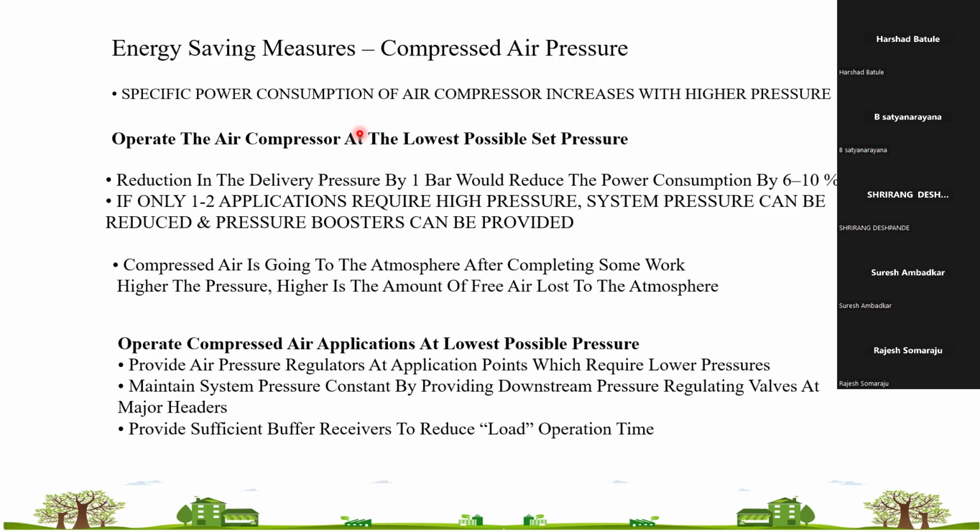That effectiveness has to be there in the intercooler, so good water and good cooling tower performance have to be there in your system. And if we allow bad intercooler performance, your power consumption goes to a higher side.